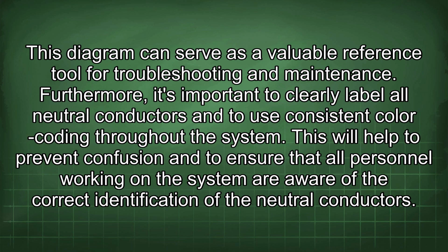Furthermore, it's important to clearly label all neutral conductors and to use consistent color coding throughout the system. This will help to prevent confusion and to ensure that all personnel working on the system are aware of the correct identification of the neutral conductors.